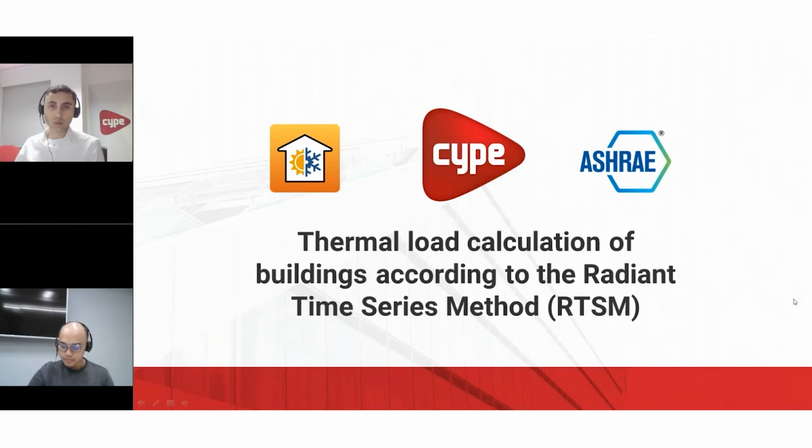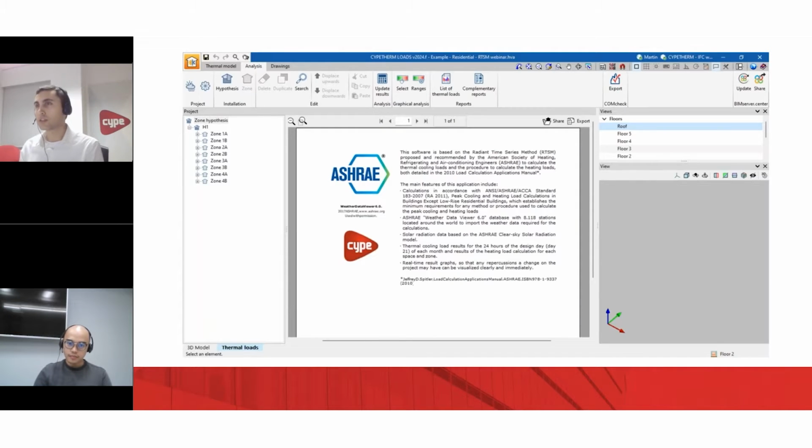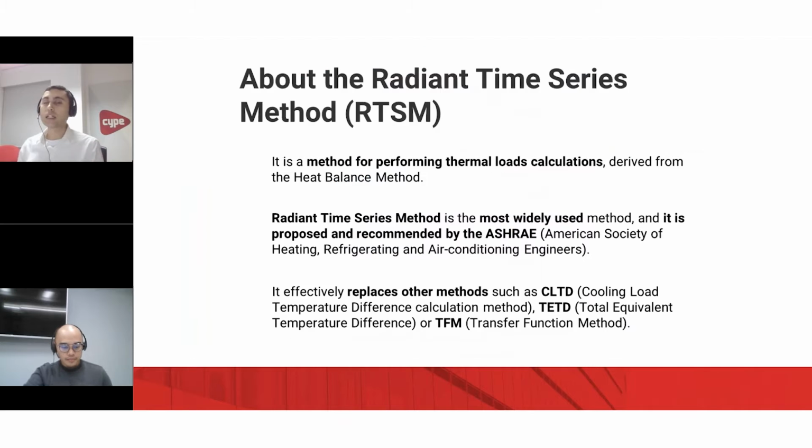And as most of our audience will know, the most widely used method is the Radiant Time Series method, which is the one proposed and recommended by ASHRAE. First of all, the program itself will explain to us how the calculations are made, or in which codes, databases, and which methodology the calculations will be based. This is a screenshot taken from the program itself.